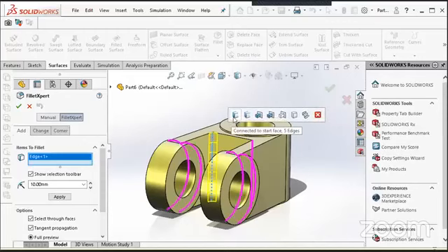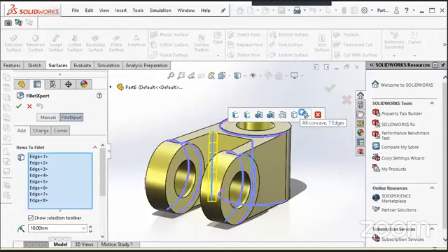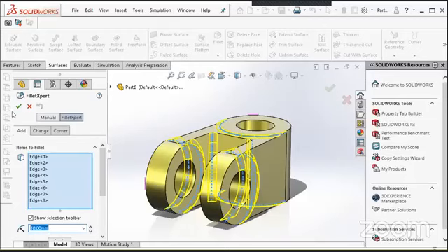Now here, after selection of the edge for the fillet, my software tells me these are the possibilities we can choose while applying the fillet. So connect to the start virtual loops. It is already highlighted in pink. Internal to feature, connected edges, and you can see that it is giving you the value of 9 edges as well. So in my case, I will select all 7 concave edges and give the value of 7 millimeters.